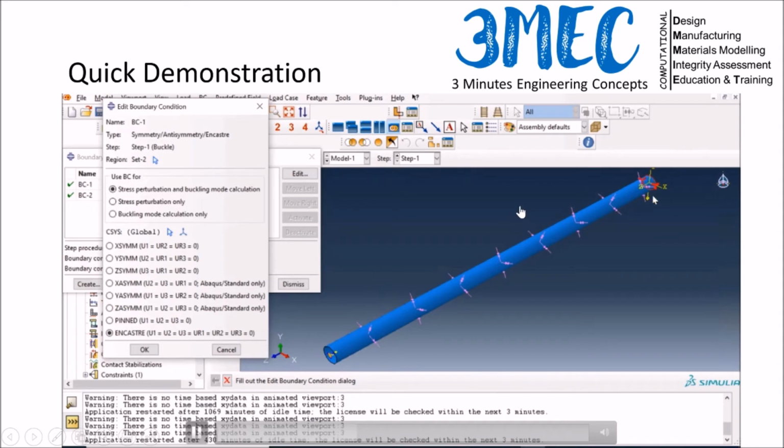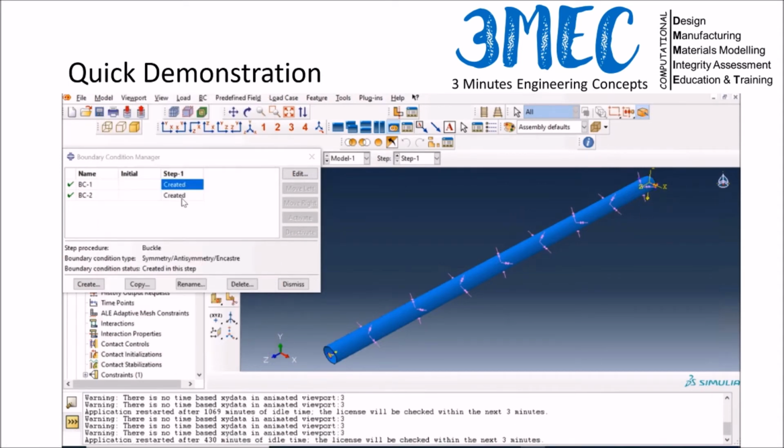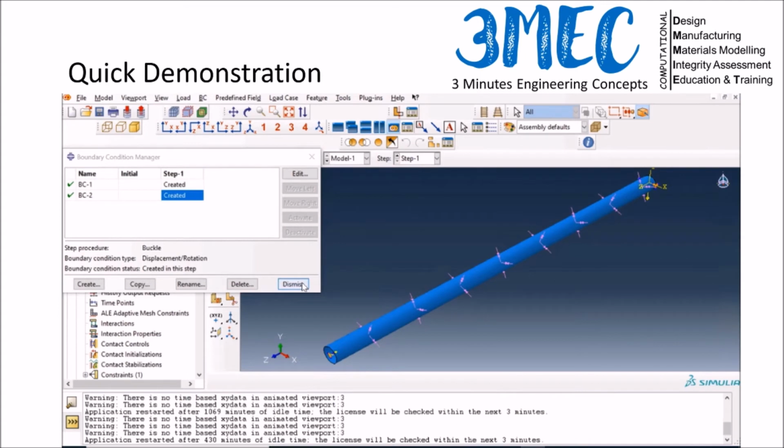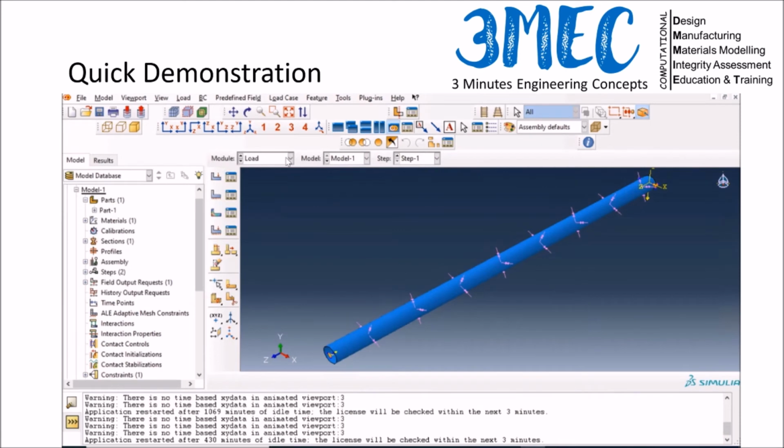As I told you, this is basically based on the fact that I'm assuming the other end to be an anchor point in my pipeline. And for this point also, I'm not allowing it to move in any other direction than the longitudinal direction or axial direction. So I'm fixing all the other things. Again, in reality, if you have the data that your pipeline can move around in lateral or other directions, then you can prescribe those as boundary conditions as well, if there is any data available. So I'm going for the extreme conditions right now.